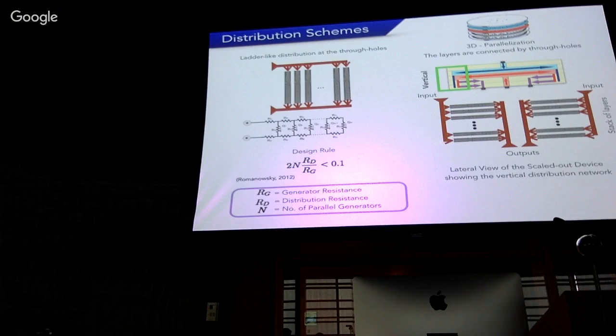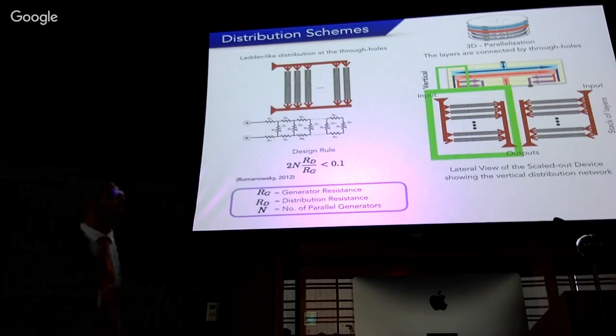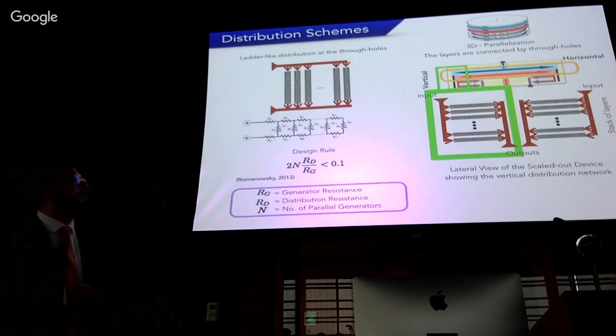And the idea is that you have different resistors here, and these resistors represent the hydraulic resistance of this feed line, and these resistors in parallel represent the hydraulic resistance of the shaft. And you want to select those resistors such that the pressure drop across this distribution network is less than 10% of the total pressure loss. So for this, we use something like that.